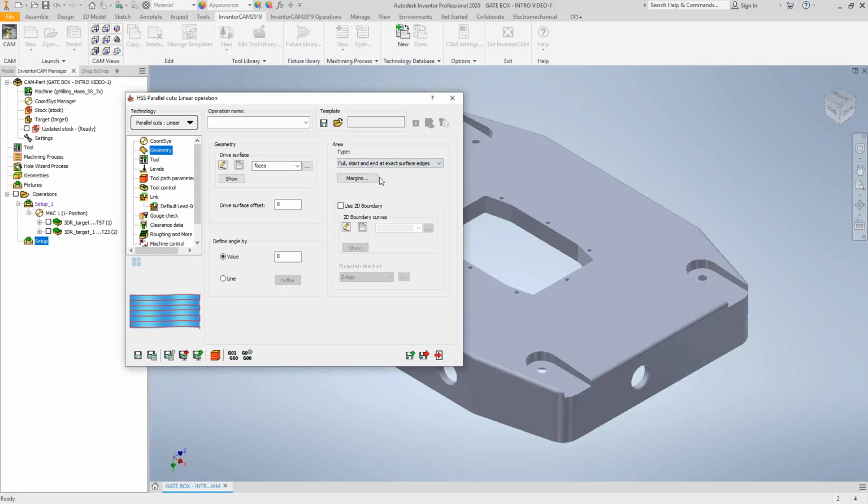It's not going to machine anything outside those surfaces, but it allows the tool to maintain a tangent point and go as far out as possible. And that's useful for things like ball mills, bull end mills, even lollipops. If you do undercutting with HSS, then you can actually tell it to go around the surface as much as possible, machine all the surface to completion while still maintaining the tangent point. So it's a good way to make sure there's no burrs or anything like that at the edges of your surface.